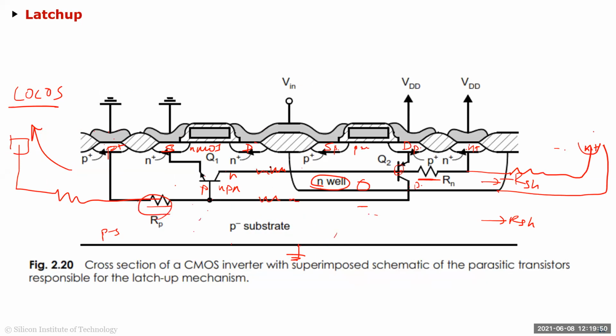All this other resistance is not an issue. Actually, it will help you prevent a latch up. But the resistance from this fictitious base to your source connection is the problem.